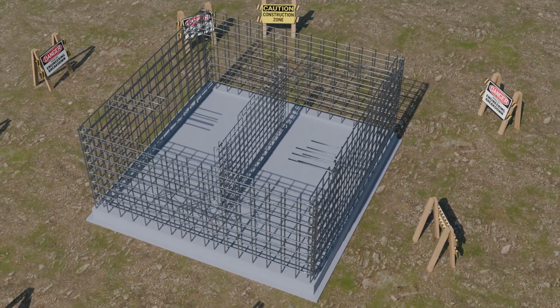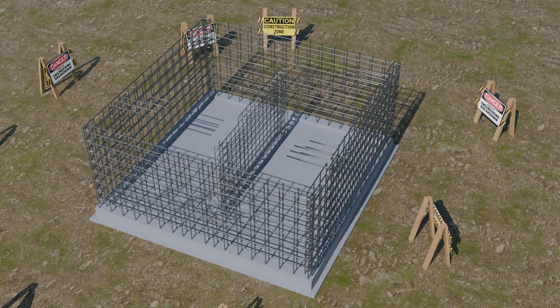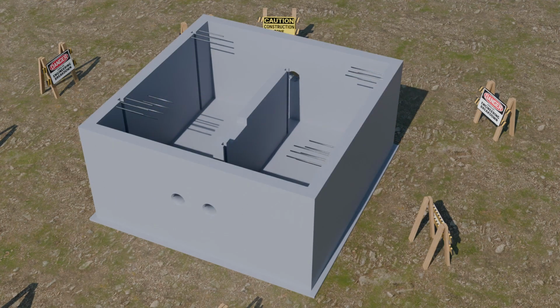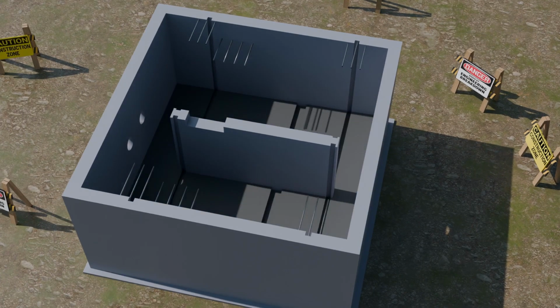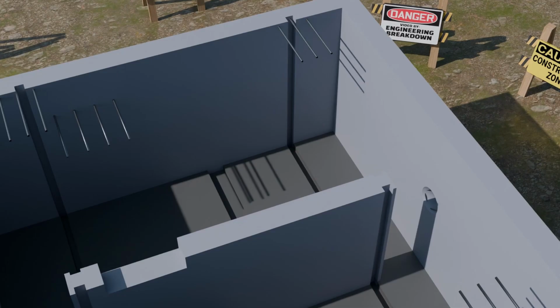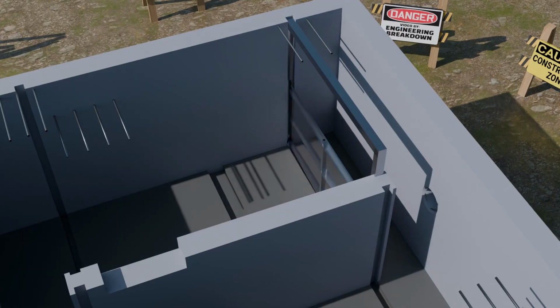Now that all reinforcement is properly placed and checked, the wall concrete can be poured. PCC is then poured at the bottom of the slab area with the required slopes and specially formed indentations for the gate systems. These recessed portions are carefully shaped to accommodate the installation of mechanical gate slots and screens, ensuring proper alignment and operation of the gates during service.